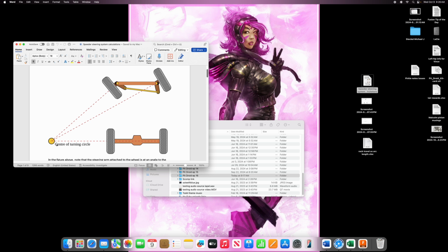If you don't have that common center point, for example, if both of these wheels turn the same amount, the one wheel would have to, it's called scrub through the corner, because the outer wheel is moving further than the inner wheel. So it was Lankensperger and then Ackermann that put it in for the patent, that came up with this steering arm geometry to make sure that this happened. So anyway, that is Ackermann geometry. And we want to hold to that when we are steering our speeder.